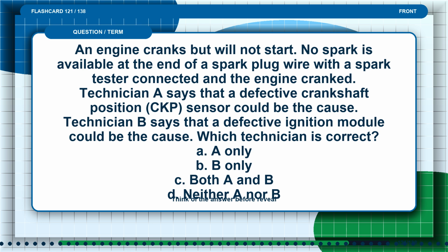Flashcard 121. An engine cranks but will not start. No spark is available at the end of a spark plug wire with a spark tester connected and the engine cranked. Technician A says that a defective crankshaft position, CKP, sensor could be the cause. Technician B says that a defective ignition module could be the cause.